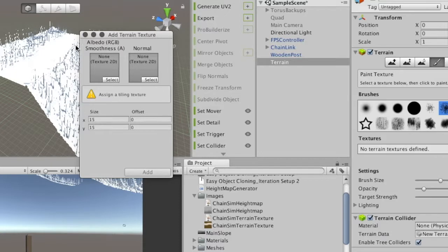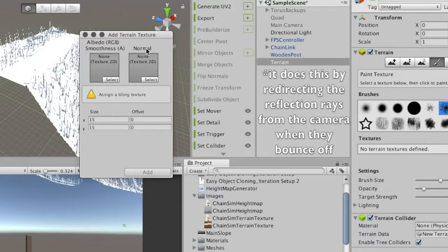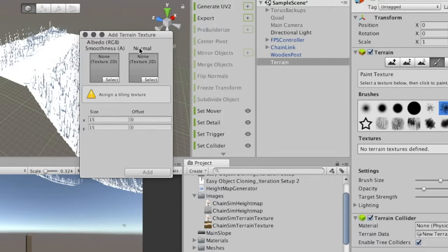As for this texture, this is the one that we are going to actually apply to the image. As for the normal, this is for bump maps. This is for if you want to assign a special image that will make a surface look like it has bump, or surface imperfections, like a bumpy surface basically. Basically it's a special image that creates an illusion of height information. So we're not going to use this because we did not design a map for that.